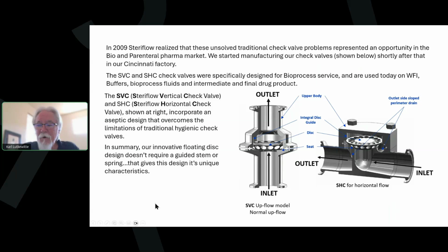It's a very simple design. There's also very little system pressure loss, because once that cracking pressure is met, it's minimal, hundredths of a PSI. Once the cracking pressure is met, the flow causes the disc to rise instantly, and I go to full flow with very little cracking pressure. So those are some of the good things that come about.